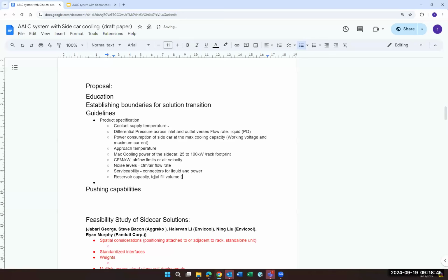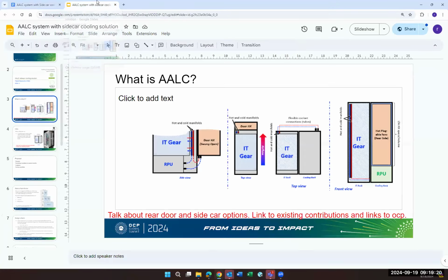Yeah, go ahead. In this case, what about the safety? What happens if the pressure is increased or something like that? We must also take into consideration that safety valves or expansion valves or an expansion tank should be in the system. Safety valves, yeah, those are definitely also needed, like pressure safety valves.